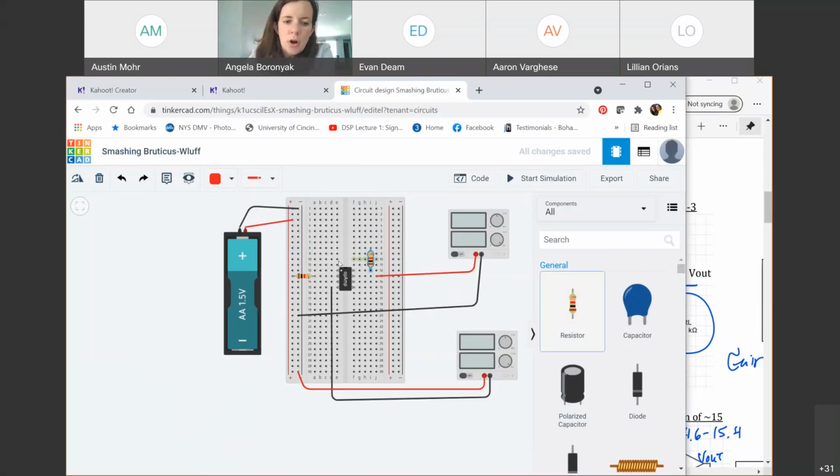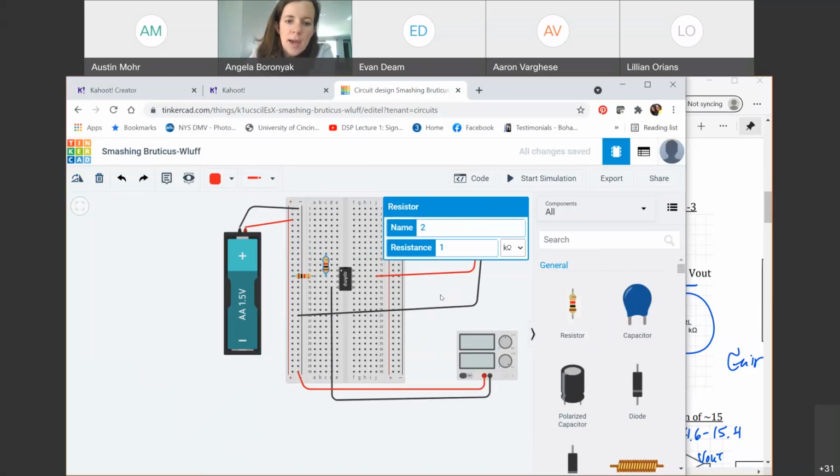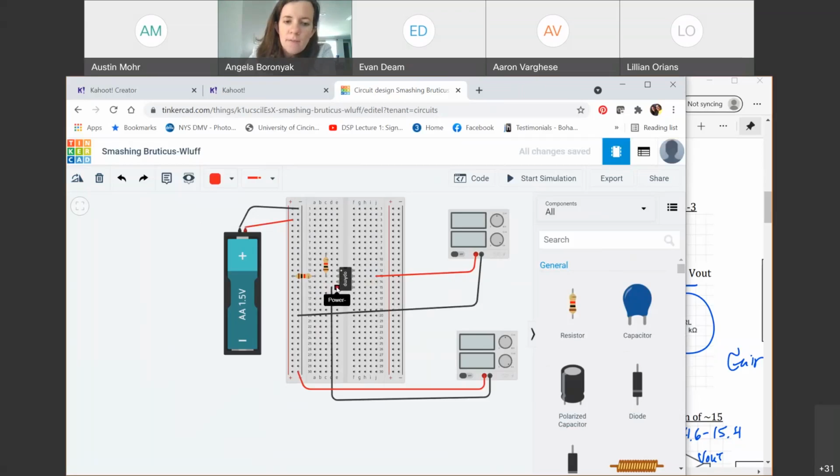And then I need a resistor also from that inverting input to go to my output, which is pin 6, or this one here. They get numbered 1, 2, 3, 4, 5, 6, 7, 8. They go up a number on this side, which is kind of annoying, but again, Tinkercad's nice that you can hover over them and it'll tell you what they are. In real life, you've got to look at that schematic and compare it.